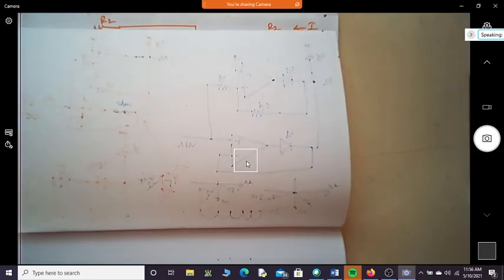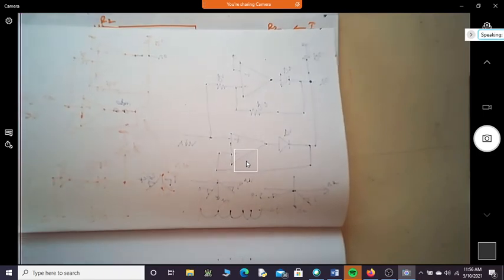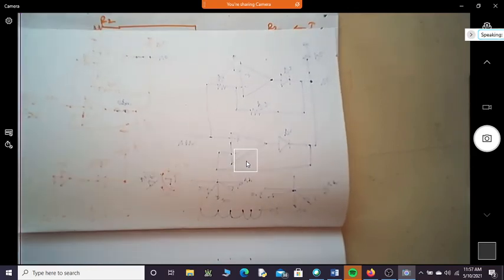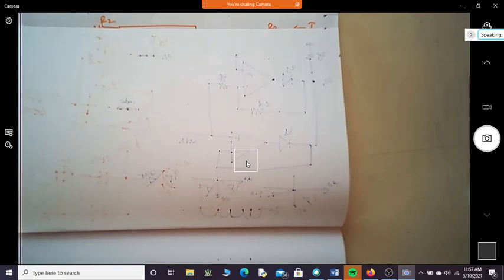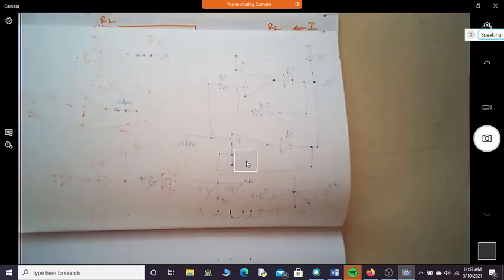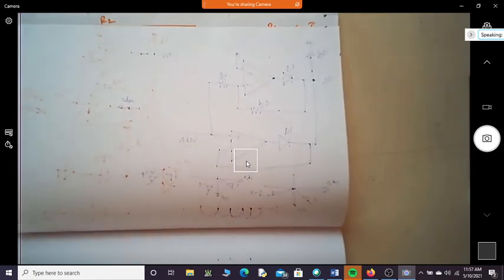If you increase the voltage beyond two-third, does the frequency reduce? If you make it below two-third, does the frequency increase? Is the frequency depending on the signal that is applied at the control voltage? If that control voltage is not given manually, but is taken from a loop filter and given to it automatically, will the frequency keep changing depending on your error voltage? That's what is actually happening in your PLL.